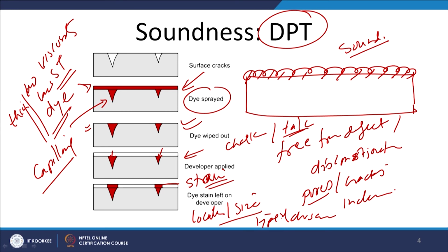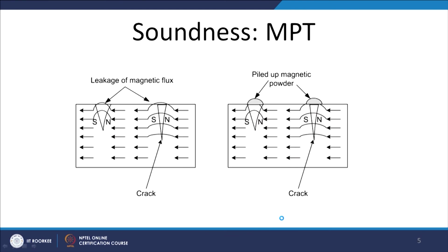Since penetration of the thin liquid into the discontinuities is mandatory for assessment of the discontinuities in this method, this method cannot detect the discontinuities which are present in the subsurface zone.